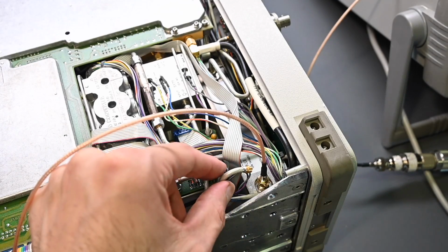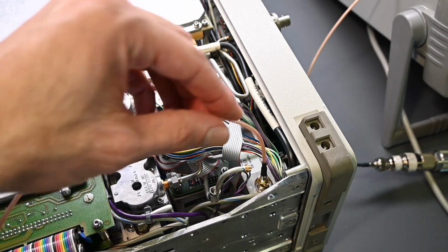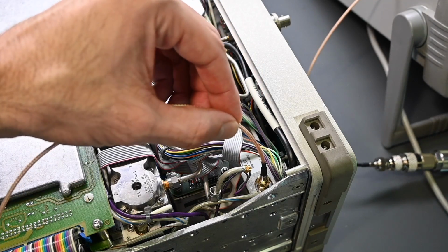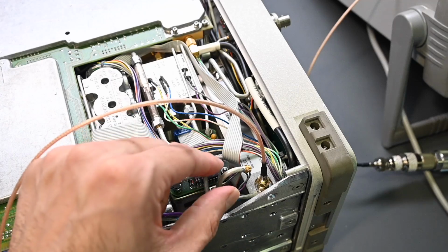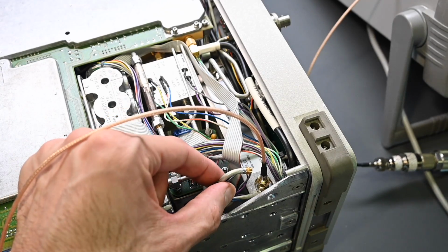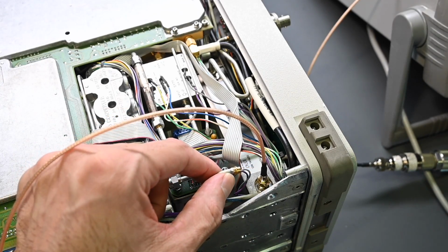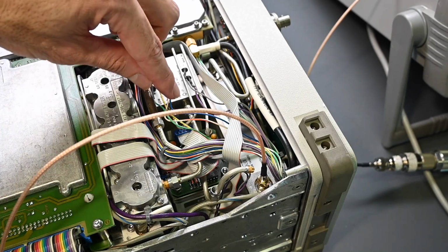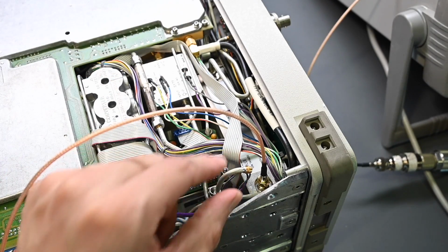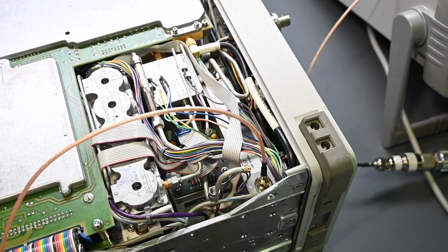So normally this rigid coax attaches to the output, but I have this coax cable attached, and this will go over to the power sensor when we do the testing. You want to be very careful with these rigid type coax cables, because you don't want to pinch them or stress them in any way. Like this one, for example, just to remove it, I've loosened the other end so that it could pivot upwards. You don't want to bend them or twist them or pinch them in any way. All right, so let me position things a little bit differently with the camera, and then we'll continue on.